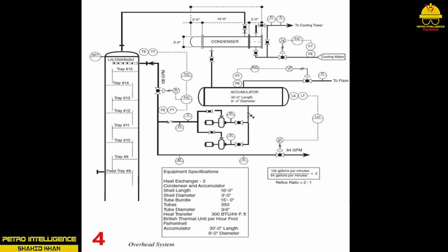This pressure control process literally backs up and controls all of the pressure on each tray in the column, top tray to bottom. The system pressure in the accumulator and the liquid feed temperature, combined with the liquid height above the reflux pump, provide adequate pressure to the suction side of the pump. The reflux pump is designed to discharge product to storage and to the top tray of the column. One control valve is mounted on the reflux line and another on the product storage line.